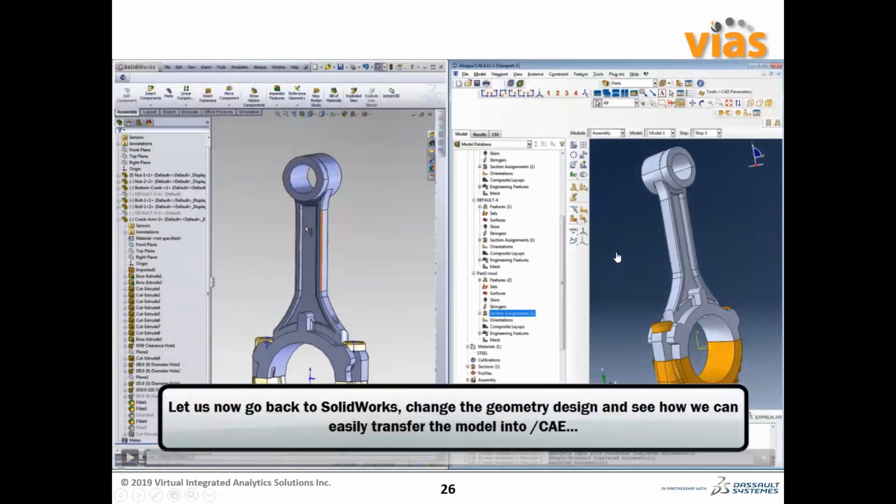But here one thing you may notice is that you can do the same thing in SolidWorks. So why Abaqus? The reason is that the actual assembly has multiple parts connected together, with different kinds of friction behavior, and contact is really difficult because there are threads and other things involved.